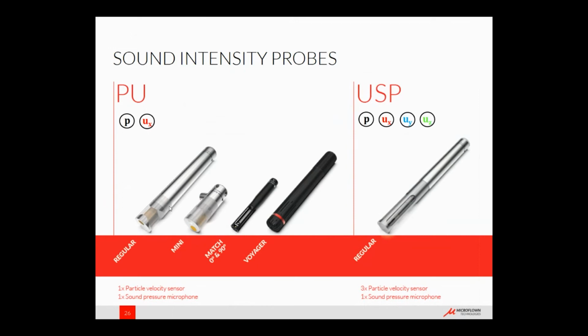Since particle velocity is directional, as we mentioned, it has a direction. We can measure particle velocity in 3D. So we also have a so-called USP probe, which is a 3D sound intensity probe. It comprises 3 orthogonally placed particle velocity sensors in the X, Y, and Z directions, as well as a sound pressure microphone. This way we can measure the 3D particle velocity as well as the 3D sound intensity, which can be very helpful as we see later on.